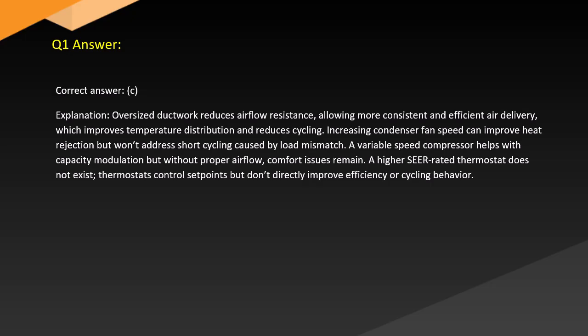A variable speed compressor helps with capacity modulation, but without proper airflow, comfort issues remain. A higher C-rated thermostat does not help. Thermostats control set points but don't directly improve efficiency or cycling behavior.